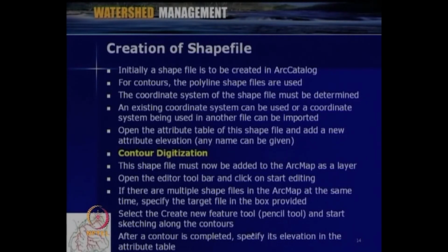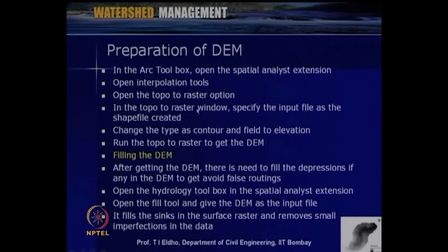After a contour is completed, specify its elevation in the attribute table. So, first is the digitization of the topo sheet, second is the creation of the shapefile, and then we can digitize the contour within the ArcGIS software itself, so that now we have the contour details with respect to the topo sheet shapefile. Then the next step is the preparation of the digital elevation model.